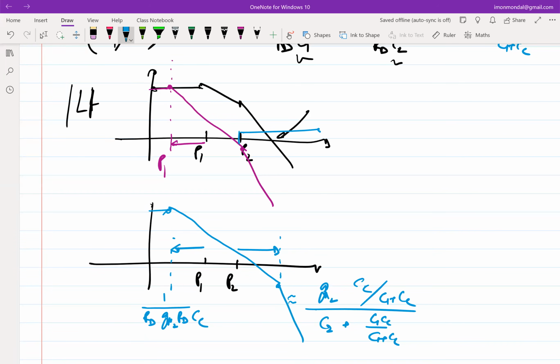So as you can see in this case also, can you comment where the new omega u loop will be? It will be at a higher frequency than the earlier one, or at a lower frequency for the same phase margin. With respect to the plot on the top, between these two, the one at the bottom I compensated using Miller. This is with Miller.